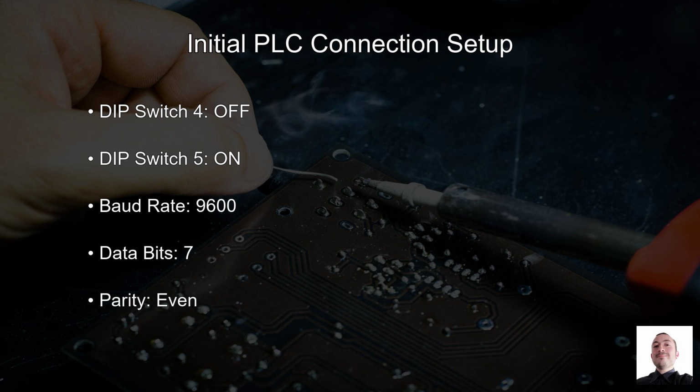If you're using a serial to USB adapter, ensure it's configured correctly, as some adapters require specific settings to function properly with PLCs. Listen carefully to these settings as they are critical for successful communication.